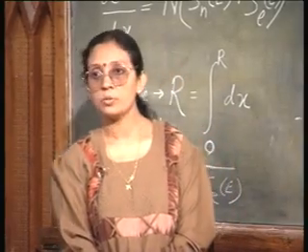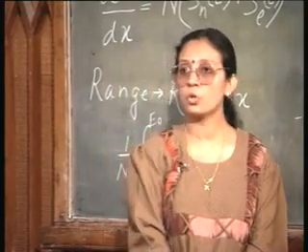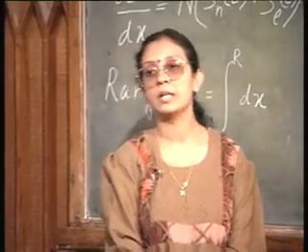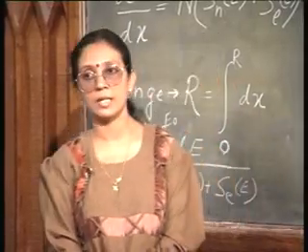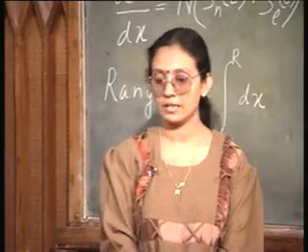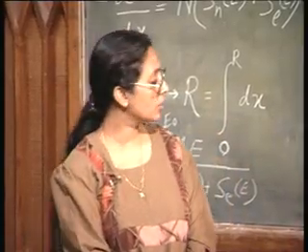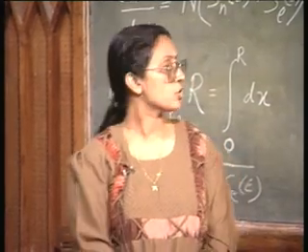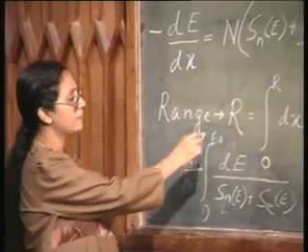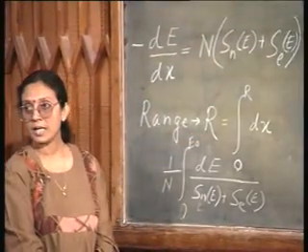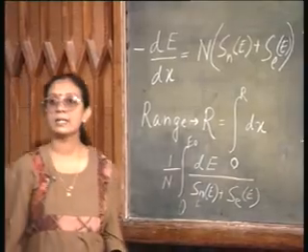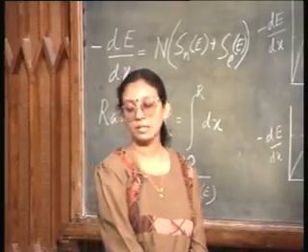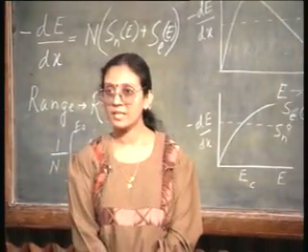So, I am going to define two zones, two regions of ion energy. When the ion energy is very high, electronic stopping is going to dominate, that is, there the ion energy is much greater than the critical energy, and below critical energy the nuclear stopping is going to dominate. So, now accordingly let us come back to the range R, and accordingly therefore, I can take one term and neglect the other so as to give me a relation for the range.